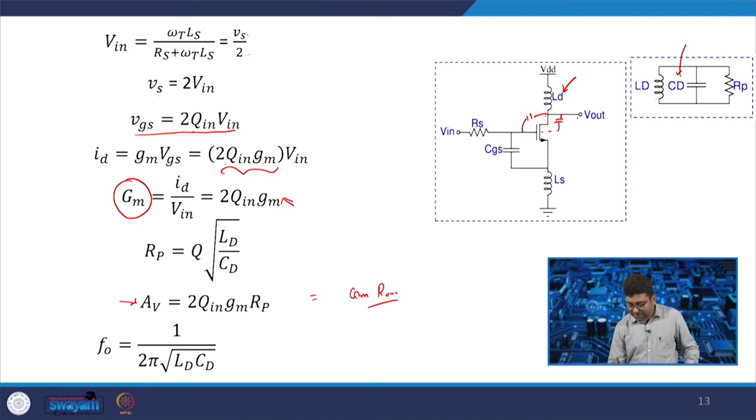So all the capacitors and the output capacitance, if you are going to drive some capacitive load, so C out also, all comprise the CD. So when there is LD and CD, because all these will not be ideal, this will represent the resonant circuit, and for that resonant circuit you can find the Rp, that is the resistance Q into LD by CD. So this is Rp.